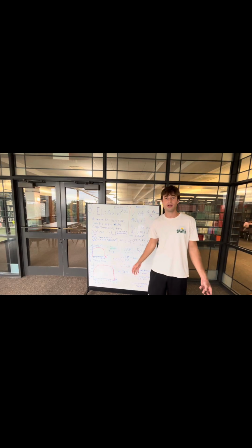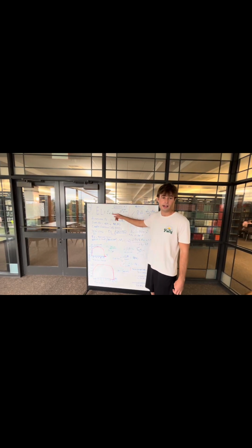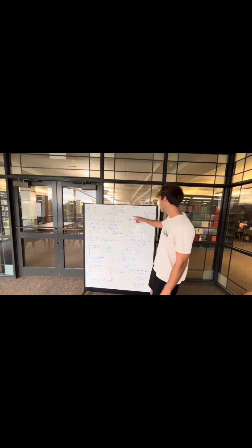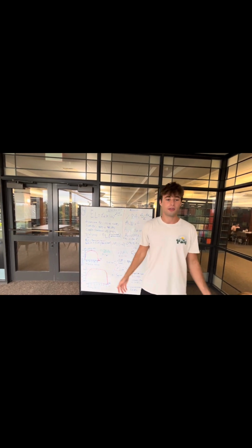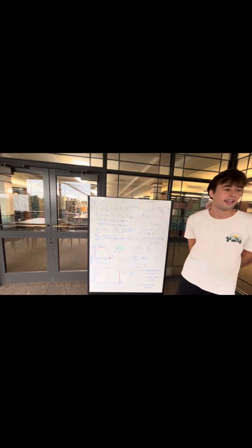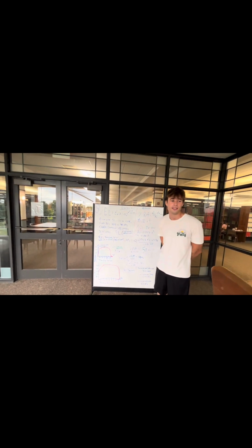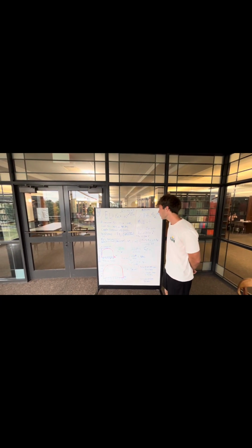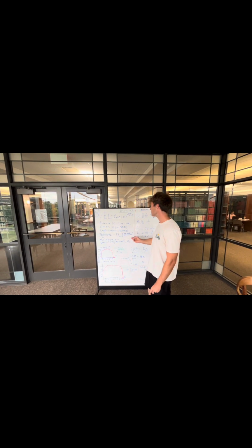There are two common ways to express ductility: percent elongation, which is right here, and percent reduction of the area, which is right here. I'll go step by step to explain what they are. Percent elongation is based on how much the material stretches. You take the change in the length at fracture and divide it by the initial gauge length, multiplied by 100. Mathematically, that is the final minus initial over initial times 100, which is how you get it if you had measuring data points.